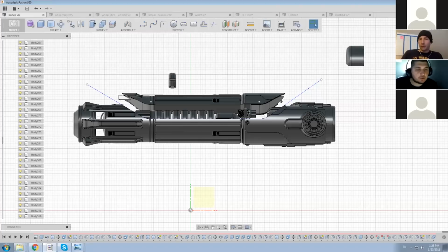I've tried doing this with Max. The best way is to export as a CAD file, because Max understands CAD files, and then do the conversion inside Max. That way you have more control over how it converts. And then you can just do automatic UVs, and that actually works just fine.